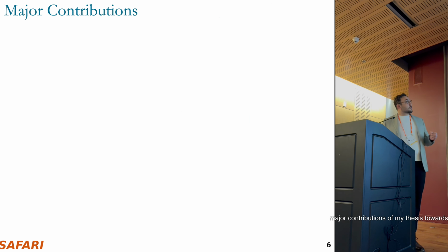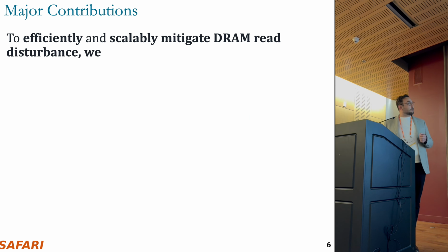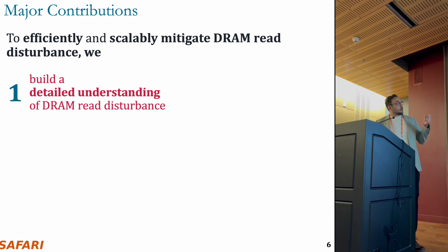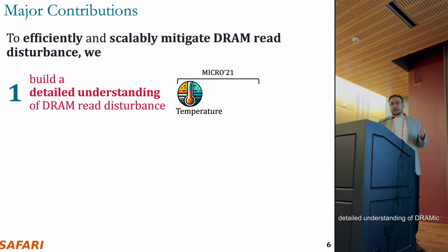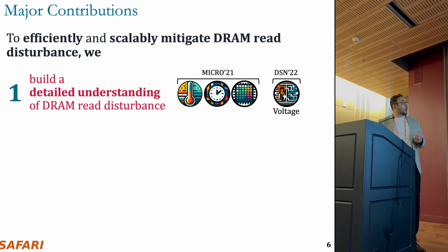The major contributions of my thesis towards the goal of efficiently and scalably mitigating DRAM read disturbance are, first, we build a detailed understanding of DRAM read disturbance. To this end, we look at Rowhammer sensitivities with varying temperature, memory access patterns, victim cell's physical location, and voltage.